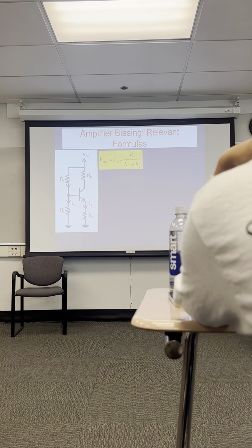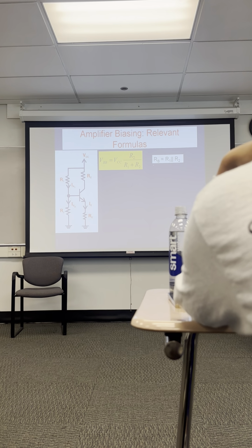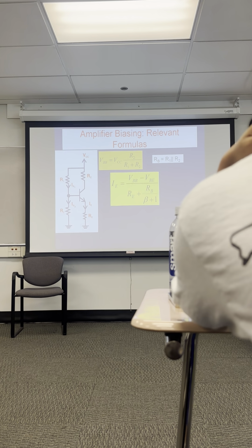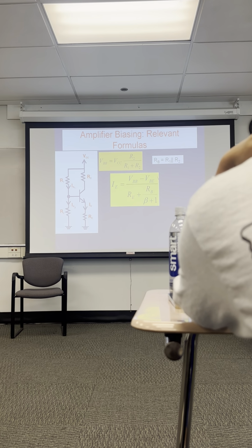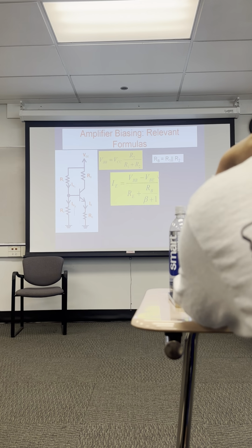So the equation that we're familiar with here is that the base voltage, V_B, is R sub B, R1 in parallel with R2, times I sub E, and make sure we have this equation. Otherwise, we have to solve the KVL around this emitter loop.